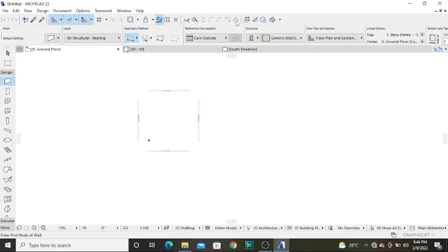And this one is used whenever you want to trim your elements that are getting to your roof. This is for chamfering orthogonal ends, and this is for ensuring that your lines, walls, and linear objects meet at an angle of 90 degrees. This one is also used whenever you want to limit the distance that your lines, walls, or objects can be elongated or moved by setting where they should reach. We also have cut, split, and many more, so please learn how to use them.